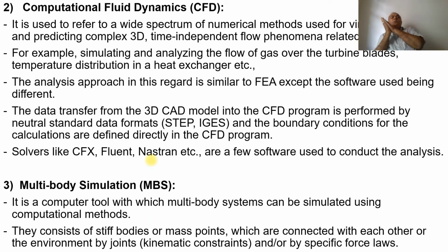So basically, the CFD model is used for the flow of gases over turbine blades and the temperature distribution in the heat exchanger. For such applications we use CFD, and it works very similarly to the finite element analysis approach, wherein the 3D CAD model is imported, the data transfer is performed by a neutral standard format, STEP or IGES, and the boundary conditions are applied directly in the CFD program. Solvers like CFX, Fluent, Nastran, etc. are a few of the software used to conduct the analysis.